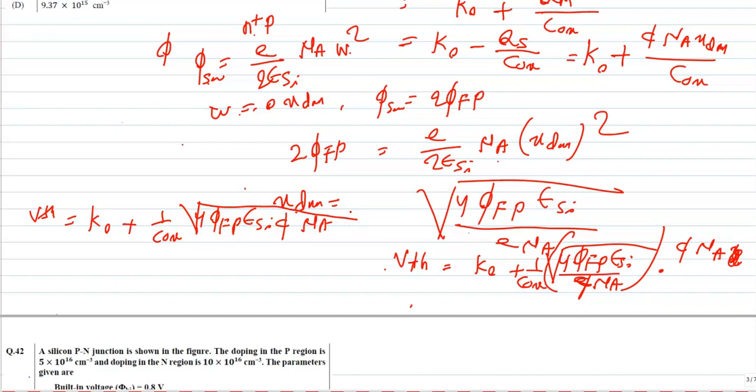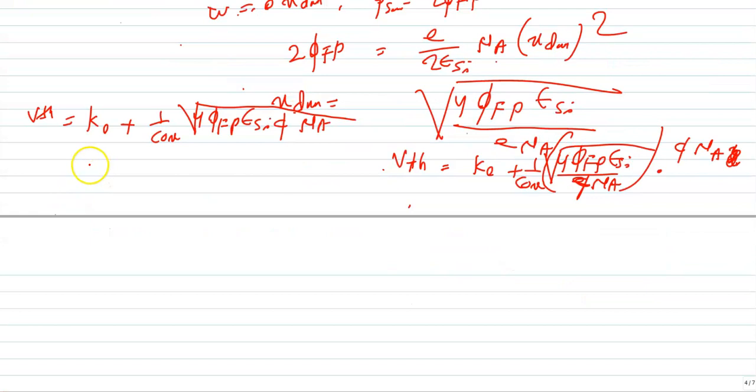This is actually a threshold voltage, but now they have applied the substrate voltage, that is VSB, obviously the reverse voltage. So that's why they have given the VBS magnitude. VSB is positive and VBS must be negative, so the negative magnitude is positive. So you know that